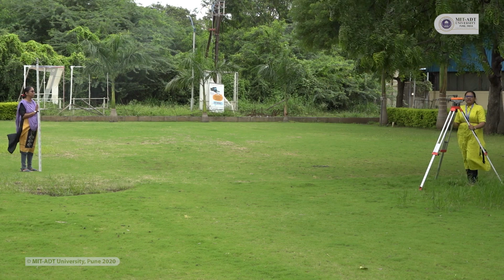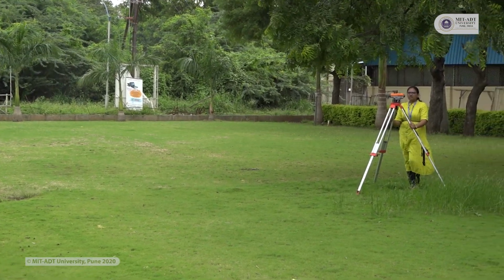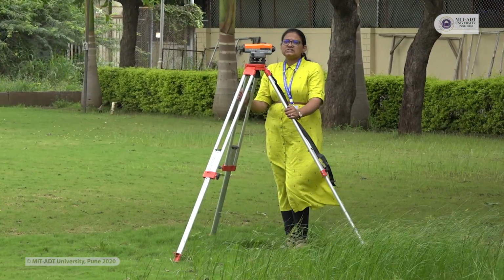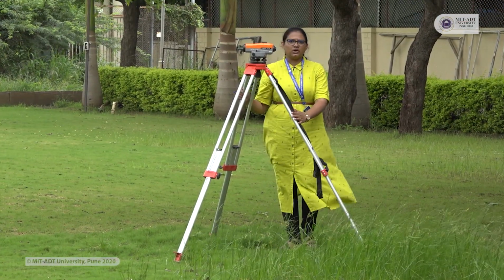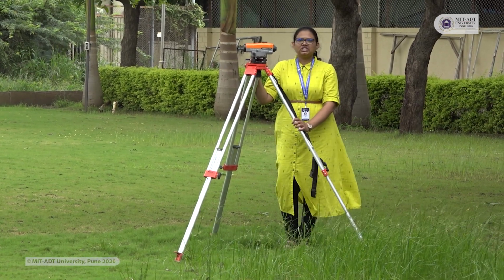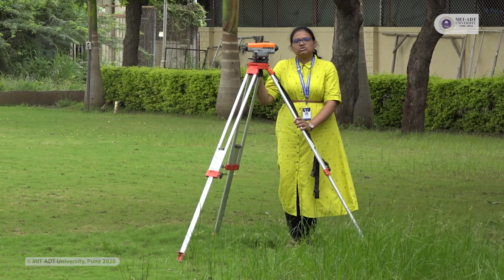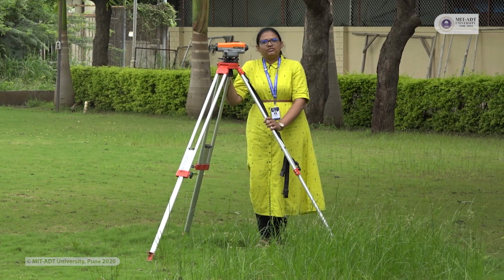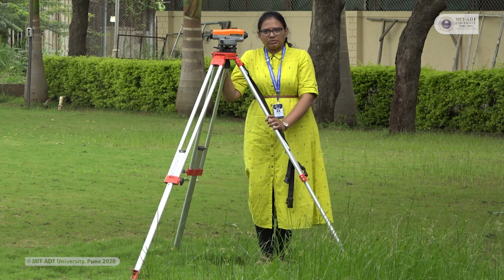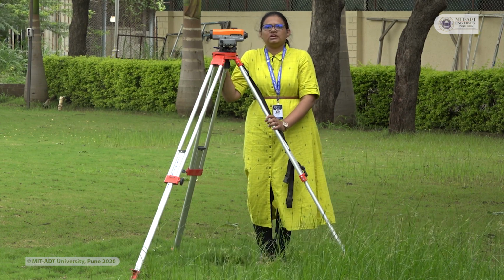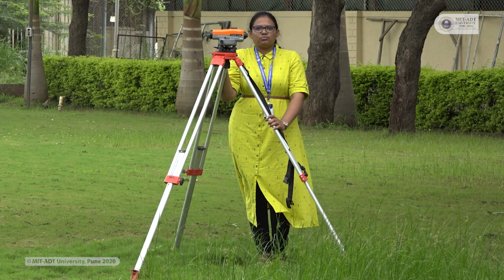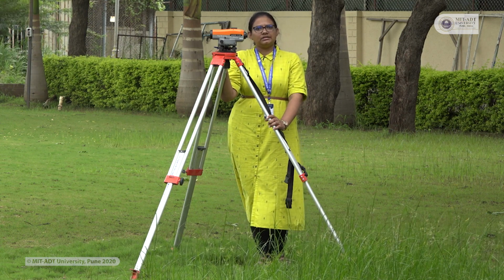Also in this way we can use this leveling for measurement of level of the ground, for measurement of different reduced levels of this particular ground. So in this way, by taking the different change points, you can measure the readings which are not accessible. So you have to use the change point when one reading is not visible to you. So you can use a different instrument station, and you can shift your instrument for measurement of the reading. Now we will calculate the reduced level of these different points for which we have taken the readings.